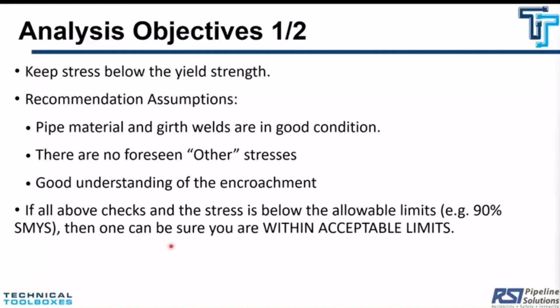The surface loading calculator accounts for the pipe internal pressure, differential temperature, and surface loading, soil overburden and the vehicular load on the pipe. If there are additional loads or stresses on the pipe from other sources, they have to be accounted for separately, right?